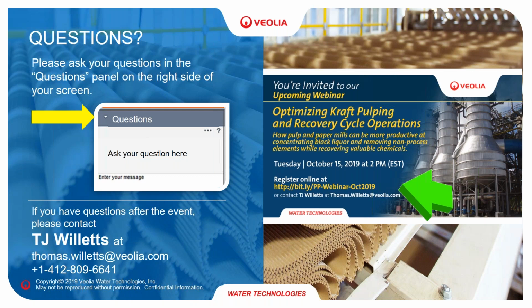So if you wouldn't do anything, then what you can see is that the calcium carbonate will precipitate in this granular sludge. The sludge will become very heavy and it will sit at the bottom, and it will be very difficult to mix it with the incoming wastewater. You will start a whole train of effects with short circuiting of wastewater through the bed, and the whole performance will of course deteriorate over time when your system is filling up with inert calcium carbonate basically.